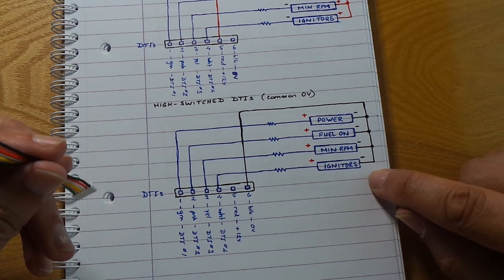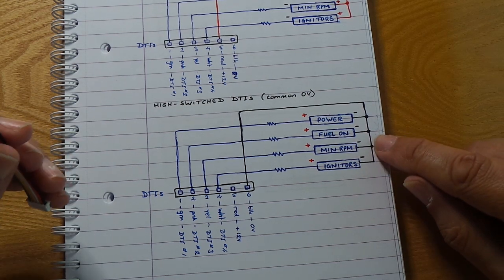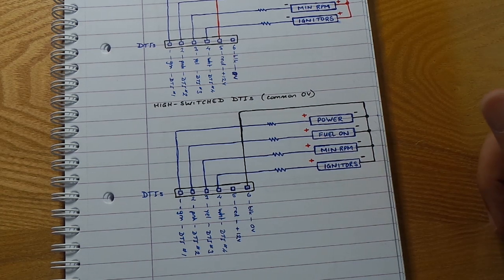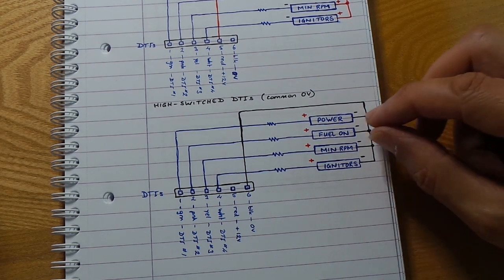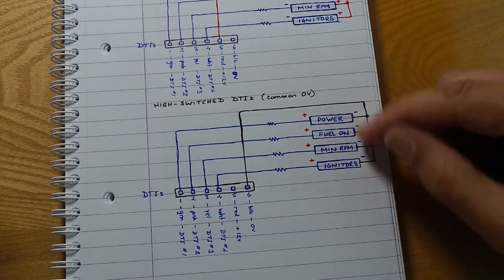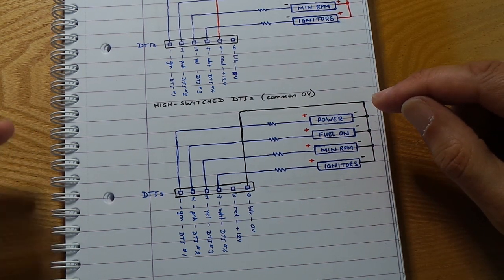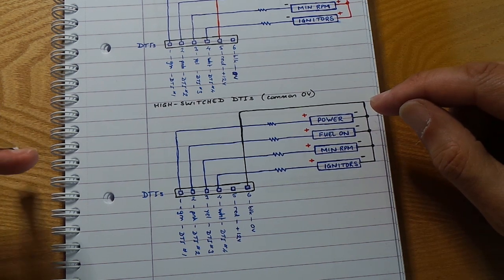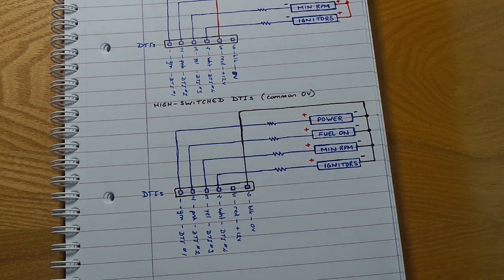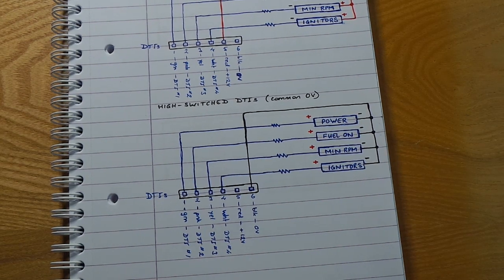Now, if you have your dash top indicators low switched and you have it programmed for high switched, or vice versa, it won't damage the unit. What it will mean is that when the indicators are supposed to start off all off and go on 1, 2, 3, 4, they'll start off all on and then switch off 1, 2, 3, 4. So if that's happening, then you need to change the polarity of the dash top indicator drive, and we can do that using the push buttons that we have connected to the generic connector. You don't need to reprogram the unit to do that now, because the latest version of software enables that to be changed over within the software.